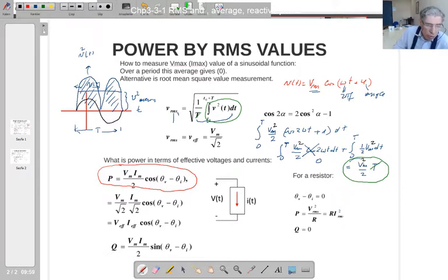So once you measure that value, you can say the value of the parameter that you are dealing with. At the beginning we mentioned that we need to calculate, measure that parameter. One way of measuring it is to find the RMS value and multiply it by square root of 2, and then you can find the maximum value.